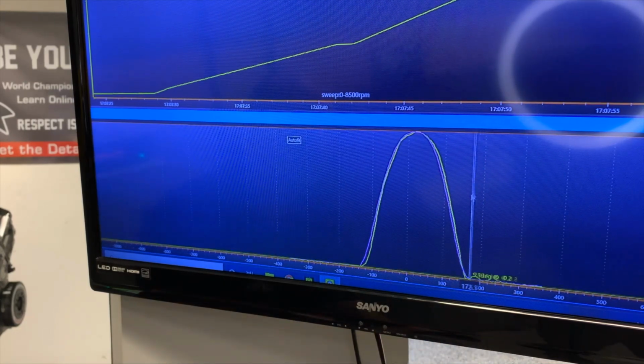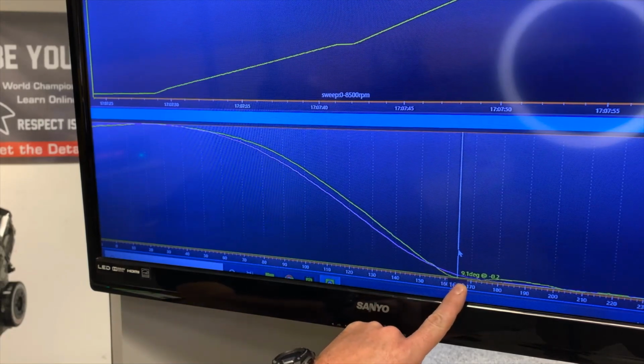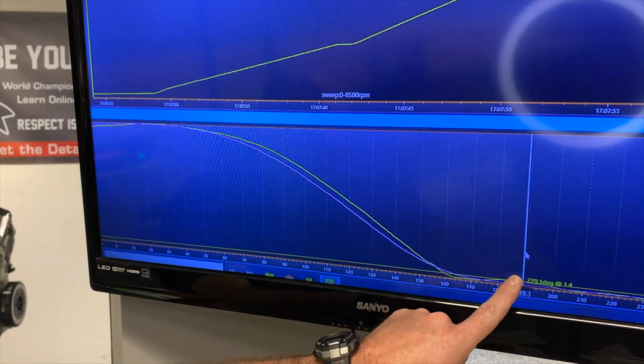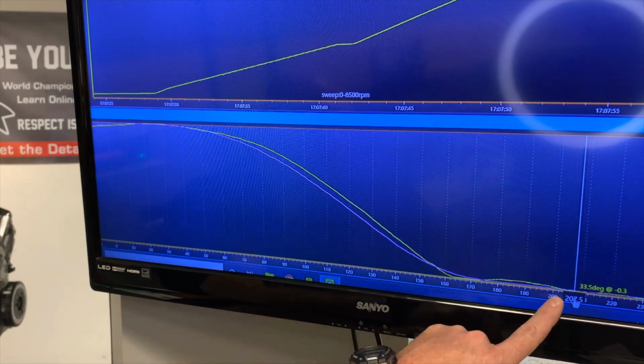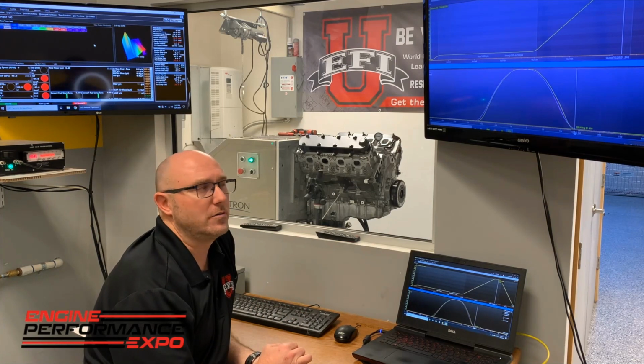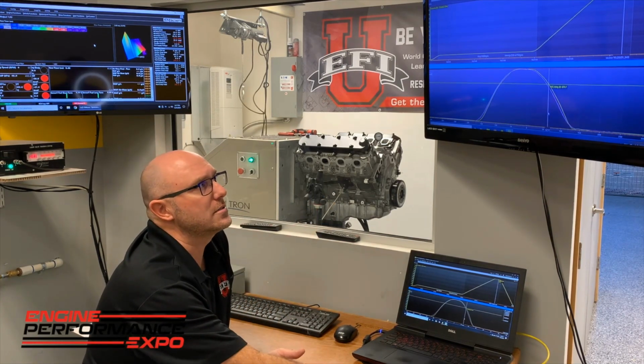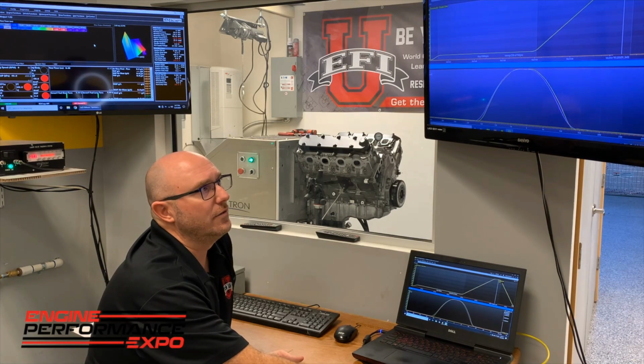The head of the valve will come to the seat, and it'll almost do like an oil can and go boop, boop, boop, boop, like that. And you'll see a negative number there where it's bending that valve under the spring force trying to hold it on the seat. And so basically that's what a Spintron run looks like. And we go through and evaluate the shape of that lobe. And we can do things like calculate the velocity.